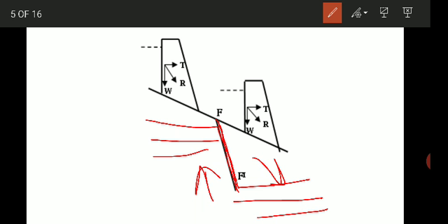So it is advisable in such cases that if you want to construct a dam in a faulted zone, then it is better to place the foundation of the dam on the upstream of the fault. So here this is safe and this is unsafe, because this part has already gone down, and if you put more weight on that, because a dam is a very big structure which involves water pressure along with the self weight of the dam.